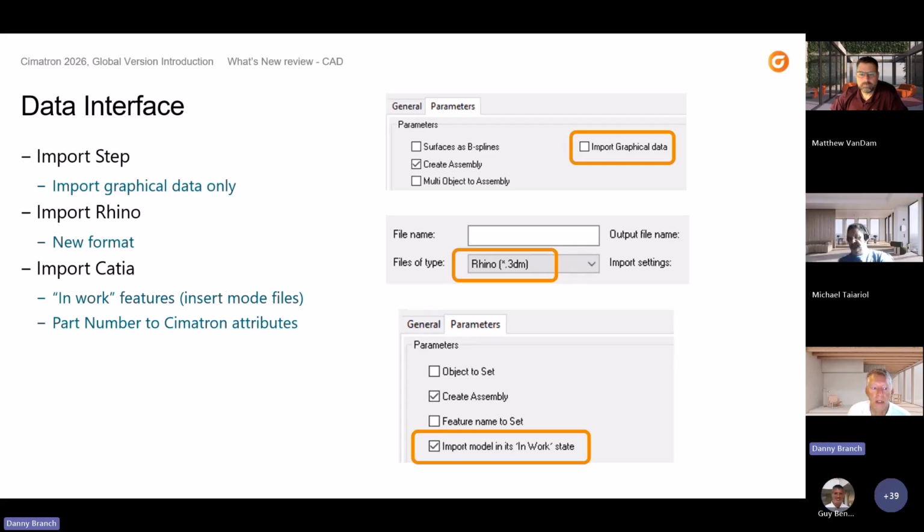It's still not an obvious situation, so something nice happens here. If you run the file, import the file, and it ends up empty, we're just going to immediately run a check to see if the mesh data is in the file. And if it is, we'll pop up a little thing that says, well, use this option, and you'll at least get the graphics. We have to do it that way because we can't just import everything at once. It's a translation thing, but it's a clever little option.